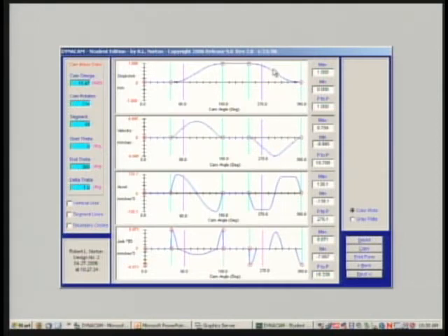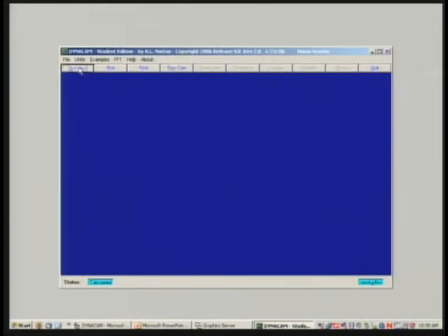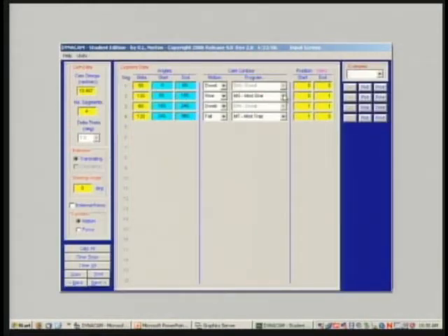So 2 integrations is sufficient to smooth out the differences. You really can't tell by looking at the displacement what kind of a function you have. You have to look at the higher derivatives. So we now have succeeded in doing an SVAJ plot. And we could go back, if we wished, and change some of these to different choices. Let's take a cycloid there instead of a modified sine, and let's take something else down here.